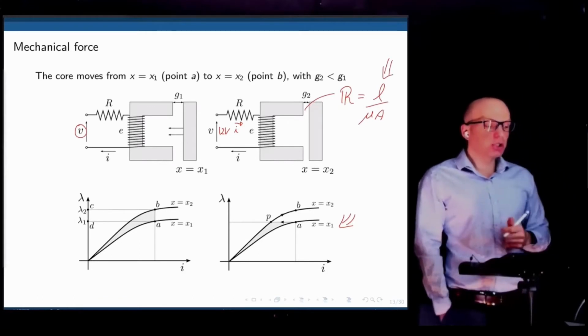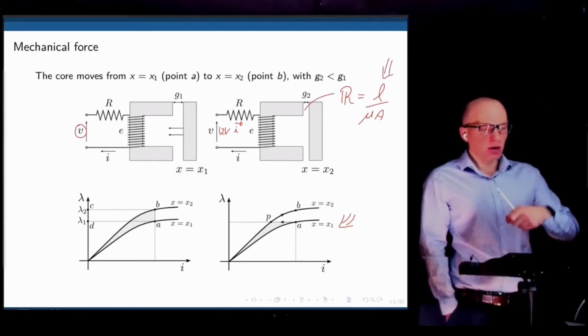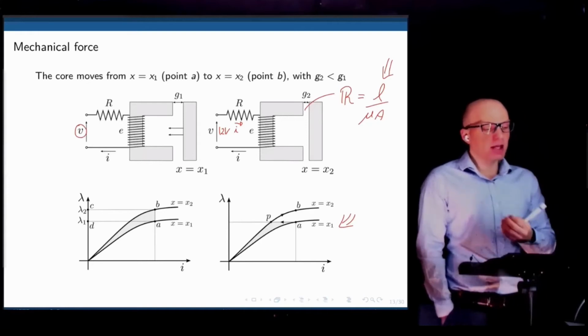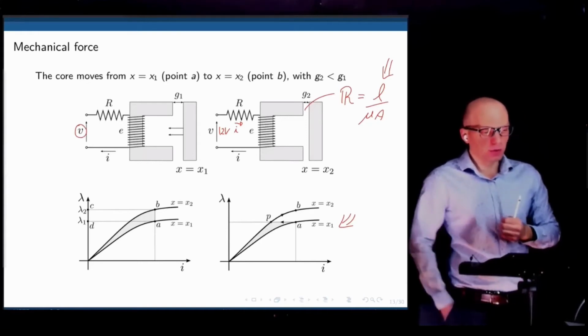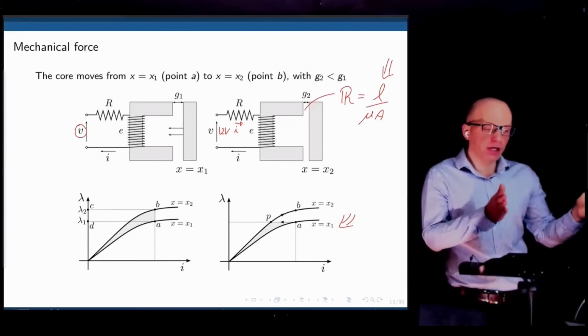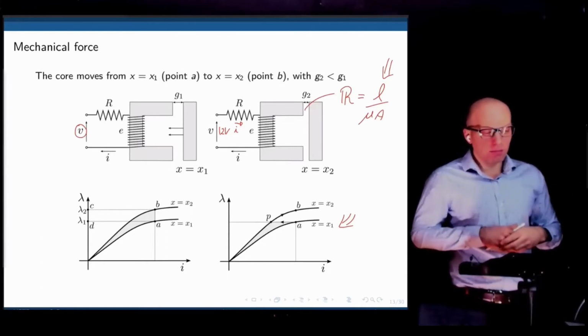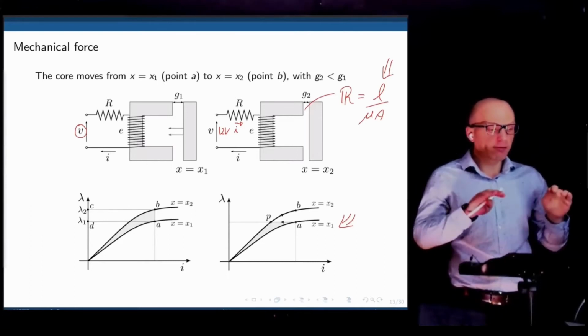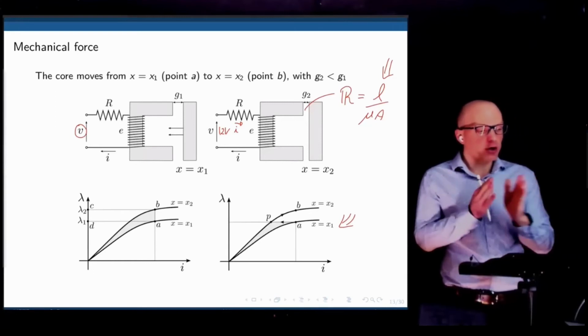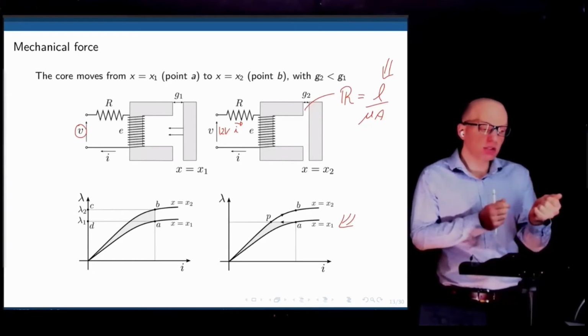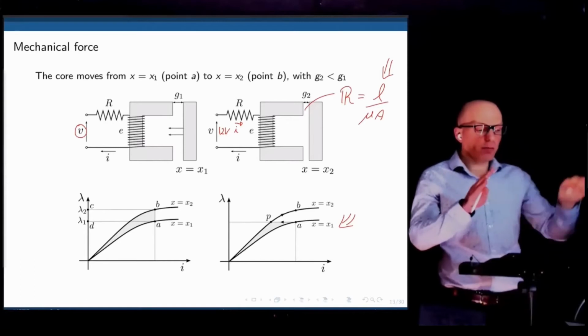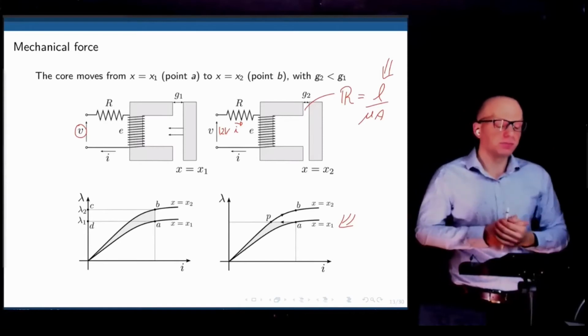We are changing the resistance to establish a magnetic field. If you go farther from the plate, there is more reluctance, and the magnetic field decreases. If you go very close, that reluctance decreases, and hence the total magnetic flux increases.